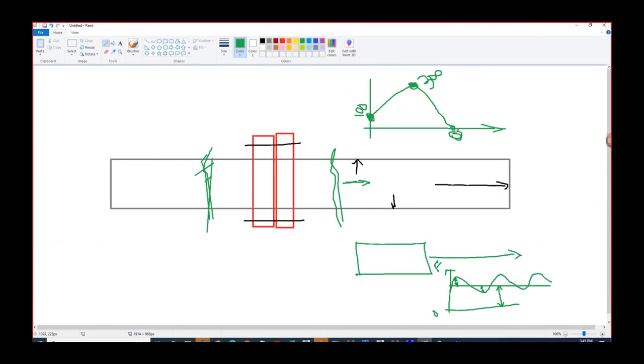From this, if you calculate the mean stress for this history of loading, you will see the mean stress coming correctly. We are not telling nCode that this is my static stress or this is my fluctuating stress. We are providing the different stress states.